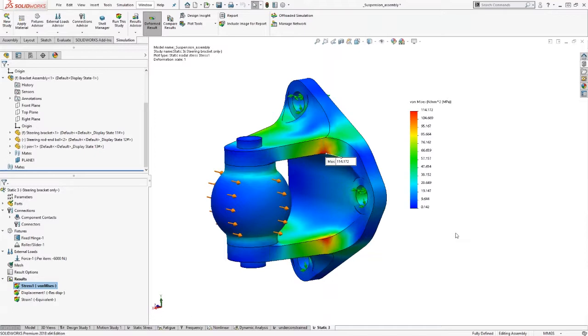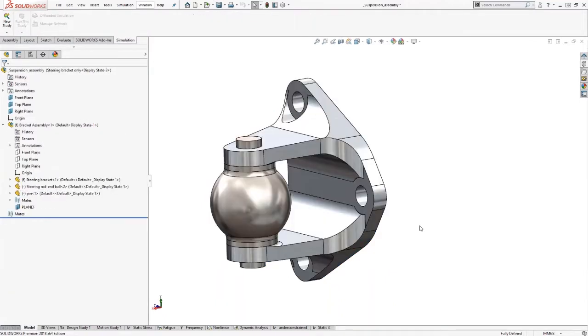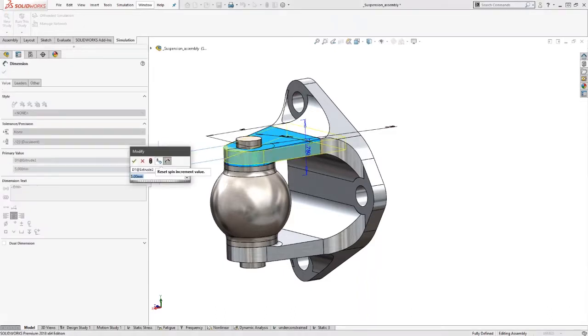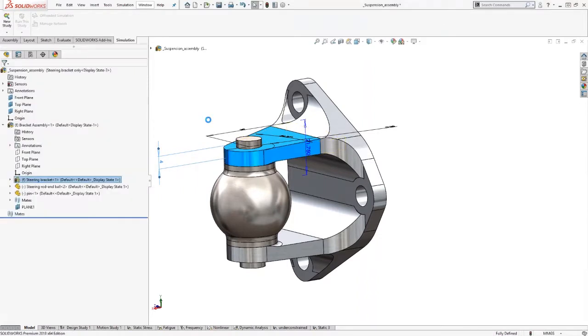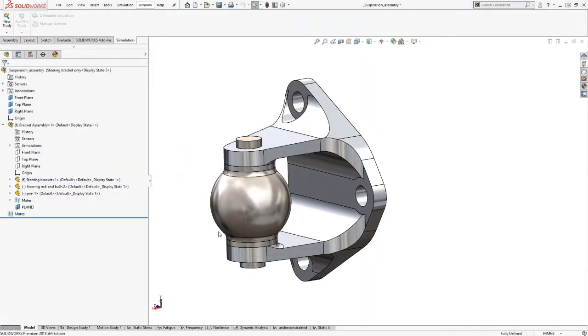Now, in my opinion, one of the best things about this tool is that, as I mentioned before, the setup is all stored on the CAD model. So now that I save this file, for instance, I can go back to my regular SOLIDWORKS modeling, and no one has to even know that there's a simulation study living on that part or assembly. And if I want to try making a design change, maybe I think I can have more stress in the model, I'll come in and I'll reduce the thickness of one of these webs, just rebuild the model, it updates.